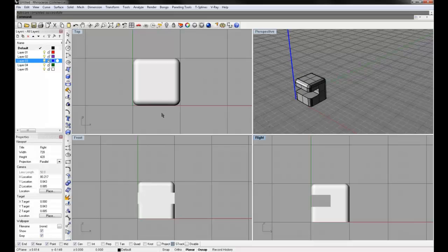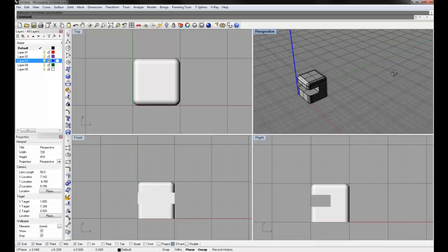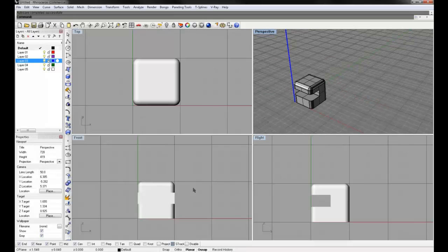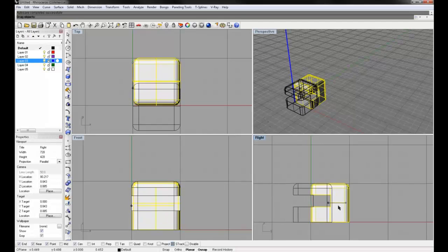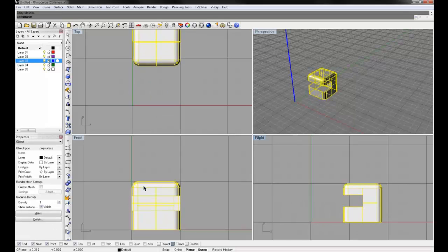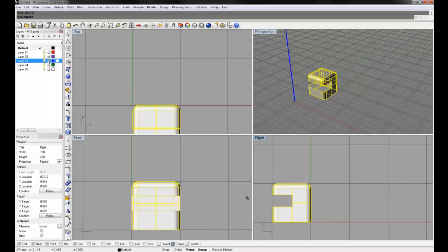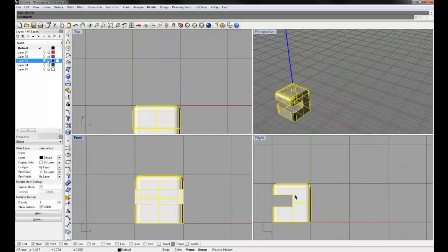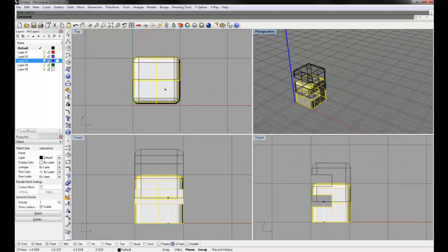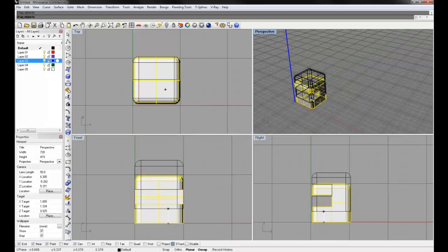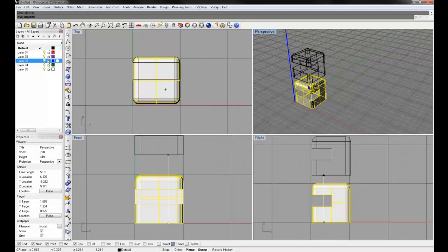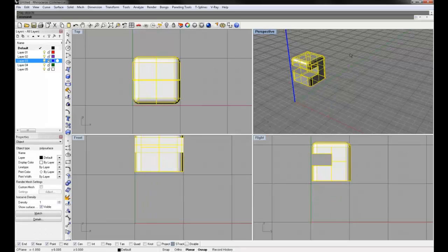So this also means that the Z-axis, as seen in the perspective window in blue, is always coming at you or coming forward. If I move our object along the X-axis in the right viewport window, in the front viewport it's not appearing to change, but actually in the front view I've changed it on its Z-axis. Likewise, if I were to move this in the perspective window up in space, I'm moving along the Y-axis in the front and right views, but in the top view I'm actually moving it along the Z-axis. Top and perspective by default match as far as their axes.